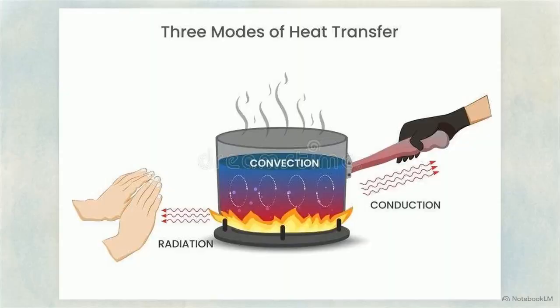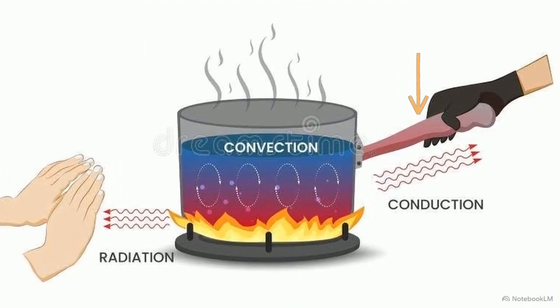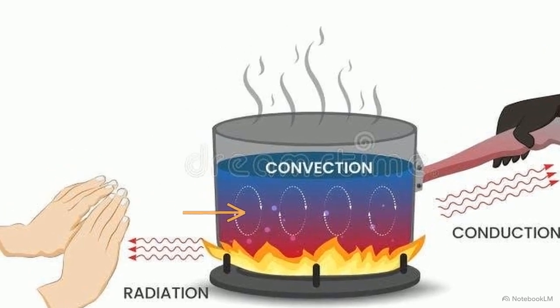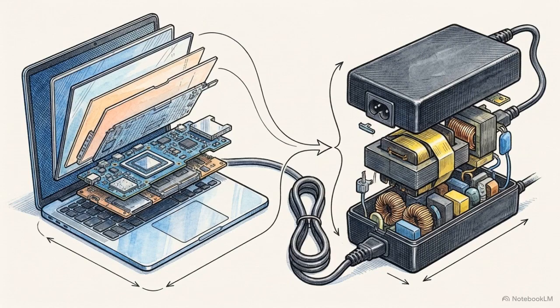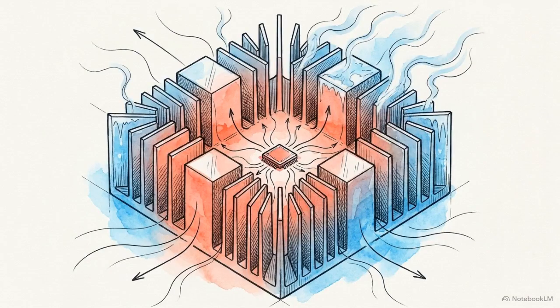To keep the semiconductors from melting, this diagram shows how thermal management systems pull heat away from the component. They rely on thick metal heat sinks to absorb the energy through conduction and then dissipate it into the surrounding air through convection. This creates a hard physical bottleneck for modern technology. We can't shrink our power adapters or industrial converters any smaller because a standard silicon chip requires a cooling system that takes up a massive amount of physical volume.